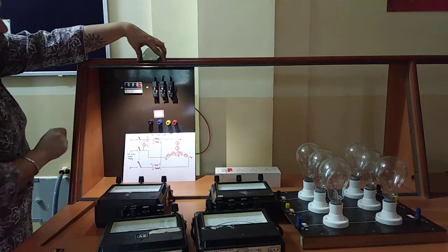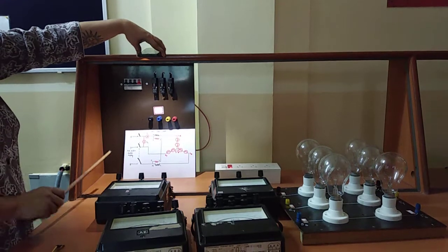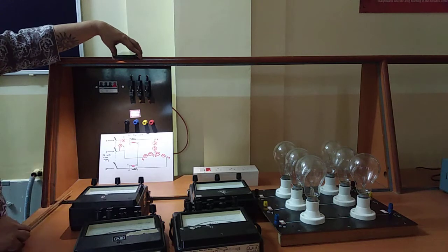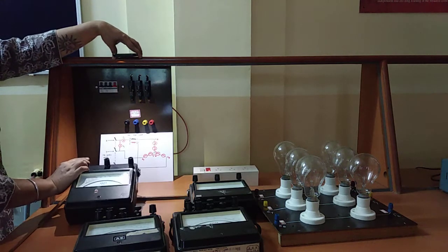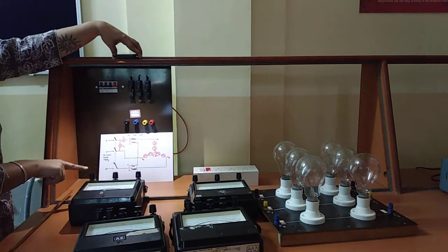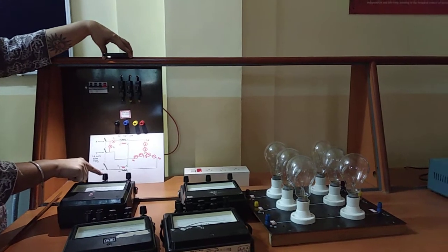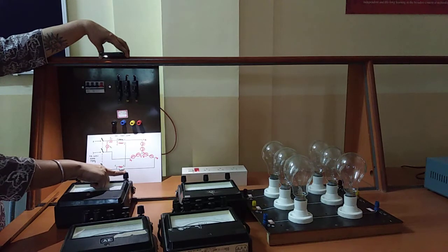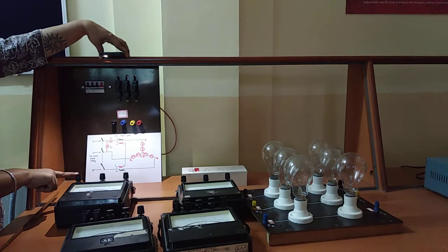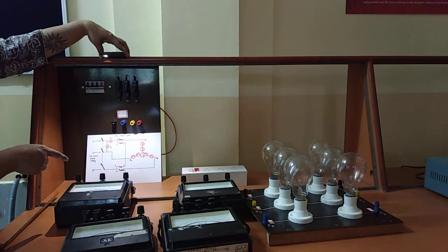And then we have a fuse for the internal switchgear protection of the whole circuit, because we're dealing with heavy voltage. And then we have ammeters and voltmeters as measuring instruments. So we are using an analog device here. This is an AC voltmeter, and there are three terminals: common, 600 volts and 300 volts. Depending on the input that we are using to measure, we can connect the 300 volts terminal along with common, because common is a mandatory input terminal that has to be connected, and you can choose 600 or 300 depending on the range of the voltage that you are trying to measure.